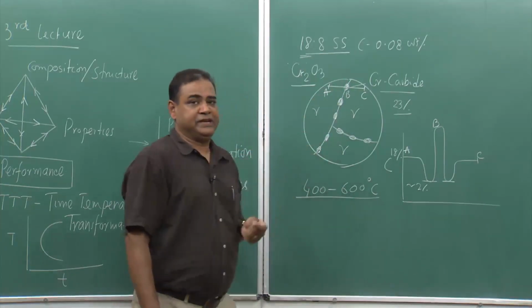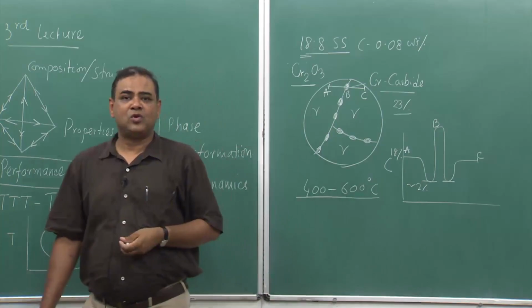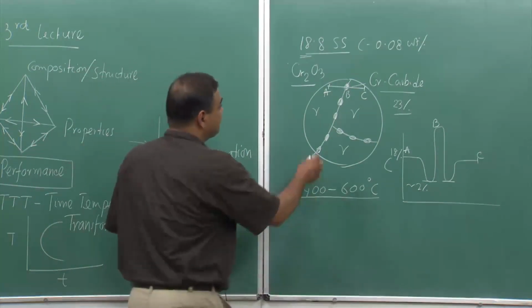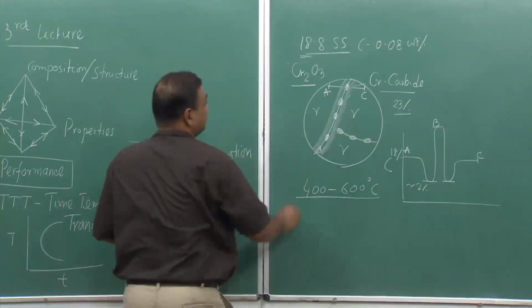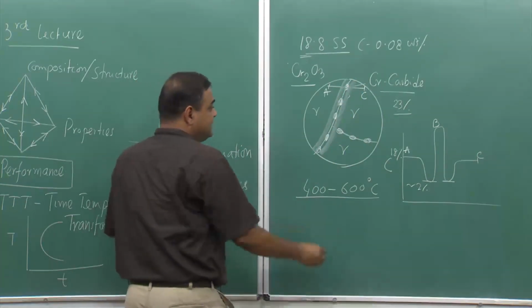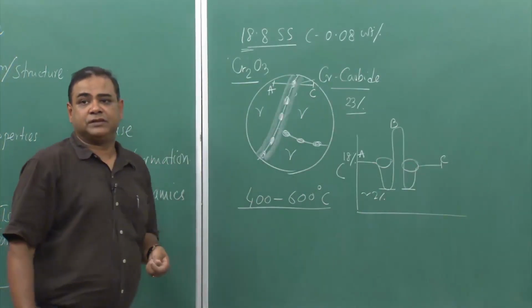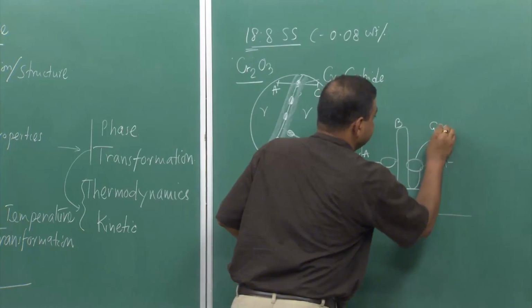Along the grain boundary, we do not find chromium oxide. If we do not have chromium oxide along the grain boundary, adjacent to the chromium oxide layer, this particular zone becomes vulnerable to further corrosion. So, this zone gets corroded.